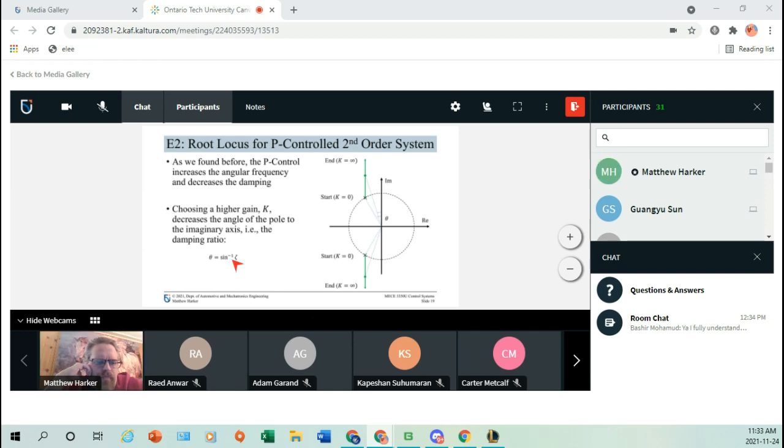Right. So that's basically things we knew already, right? In terms of just mathematical formulas. That, you know, changing the Kp for our feedback is changing the behavior, and this now shows us graphically in that Laplace domain what's going on, right? So why the angular frequency is increasing and why that damping is being decreased as we increase P.